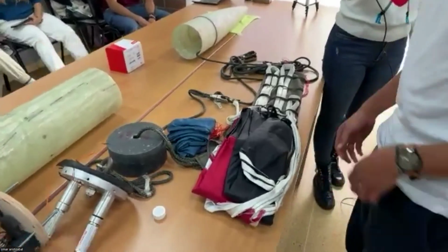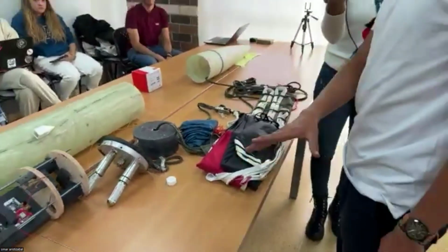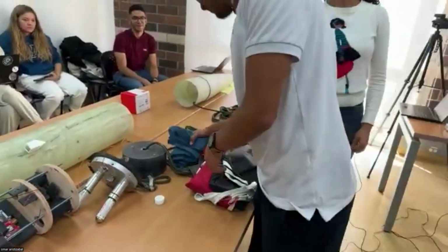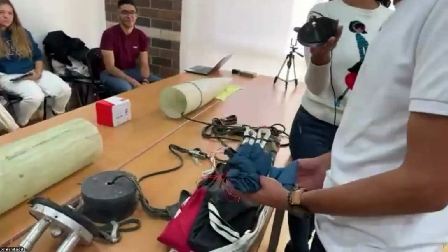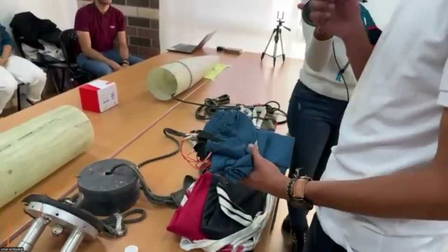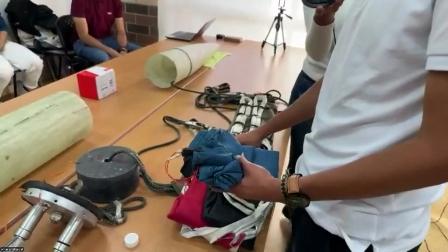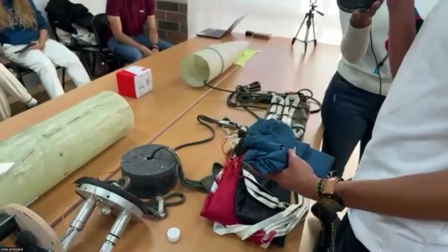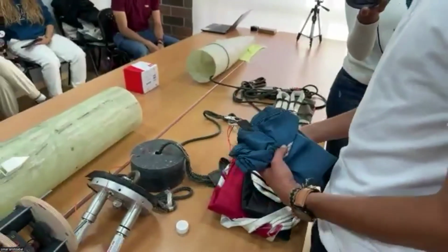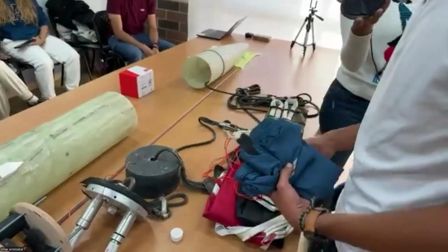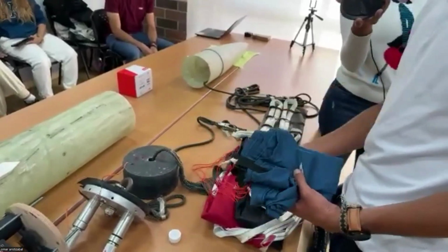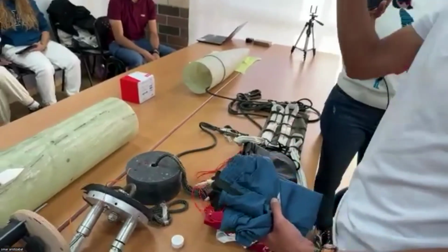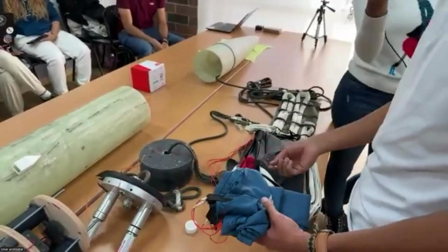Before going to the drogue, I have to make a note. We have a pilot parachute, which will help to extract the main from the deployment bag. In the recovery diagram, the drogue will be above the main when trying to deploy the main parachute.